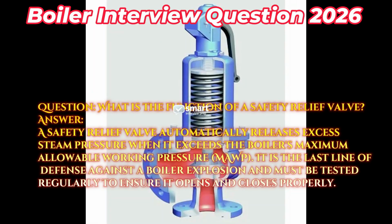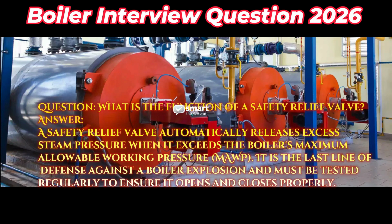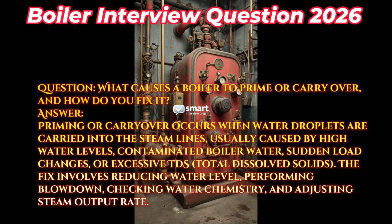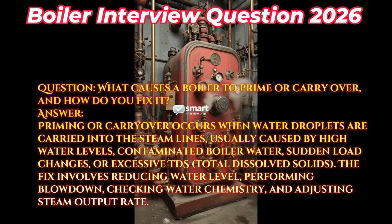Question: what is the function of a safety relief valve? Answer: a safety relief valve automatically releases excess steam pressure when it exceeds the boiler's maximum allowable working pressure, MAWP. It is the last line of defense against a boiler explosion and must be tested regularly to ensure it opens and closes properly. Question: what causes a boiler to prime or carry over, and how do you fix it?